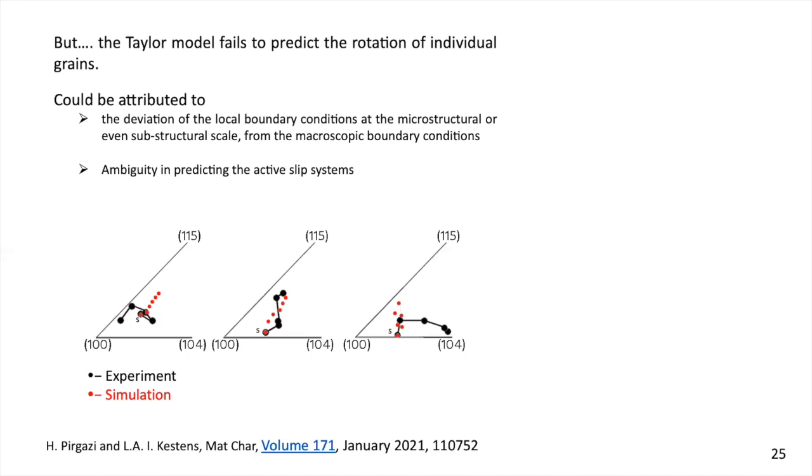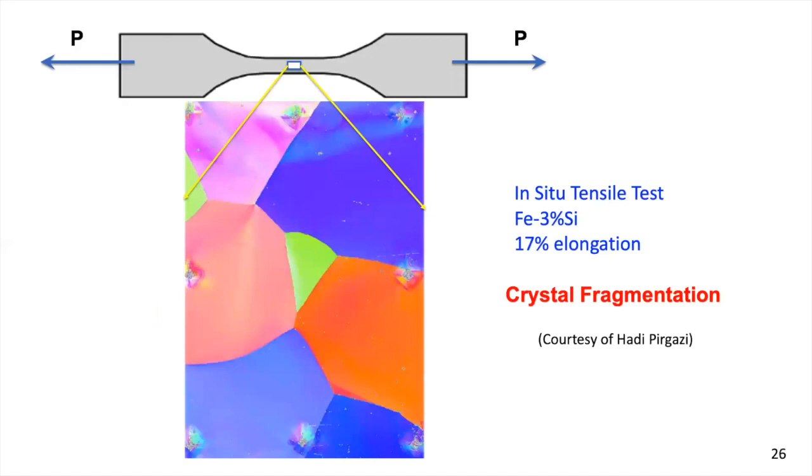But whereas the crystal orientation distribution, with reasonable correspondence, is predicted by the theory, this is not the case for individual grains in the microstructure. So that's one important conclusion we can draw from this: don't confuse crystal orientation with grain. Grain is a different concept in the microstructure than a crystal orientation. Crystal orientation may be distributed over many different grains.